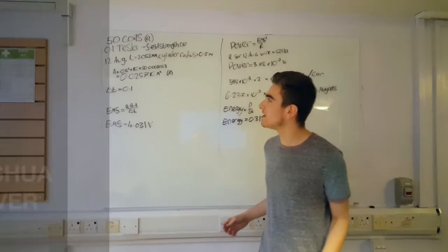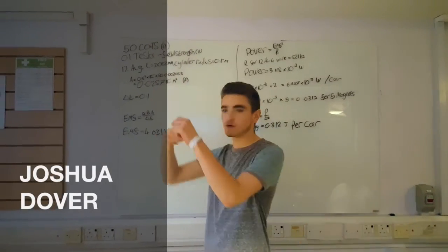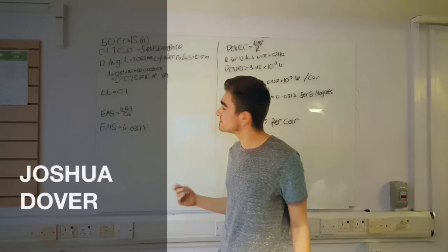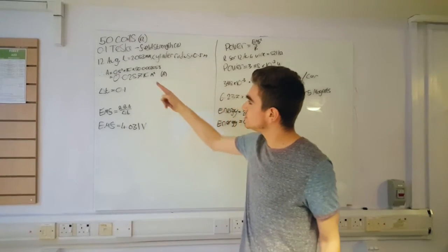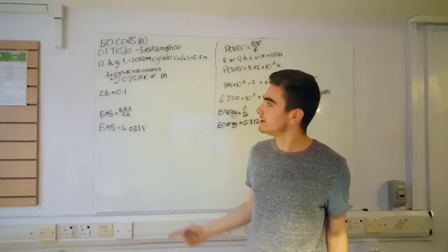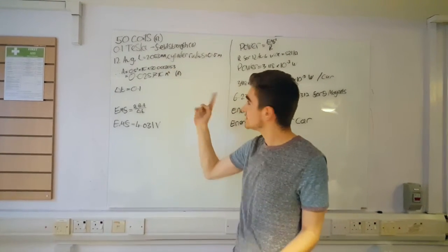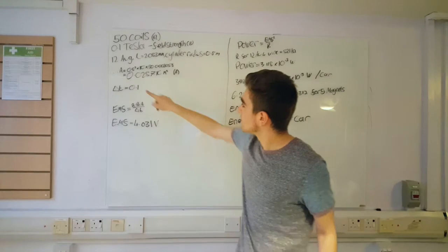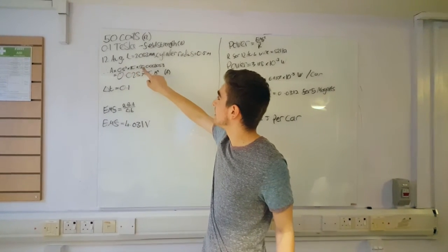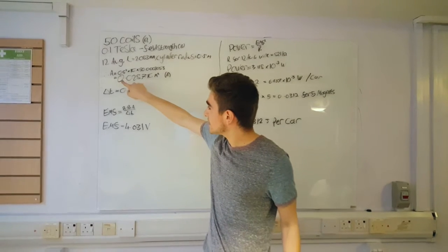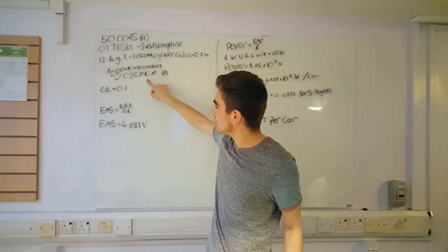Right, so for each of our coils, we're going to have 50 individual wires, so N will be 50. We're going to use a magnet with field strength of 0.1 Teslas, and we decided to use 12 AWG, 12 gauge wire, so we'll have a diameter of 2.053 millimeters, and we're going to use a cylinder radius of 0.5 meters. So working out the area will be 0.5 squared times pi times 50 times 0.002053, keeping it all in meters. It'll give us 0.0257 pi meters squared.